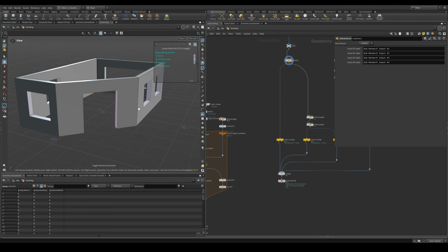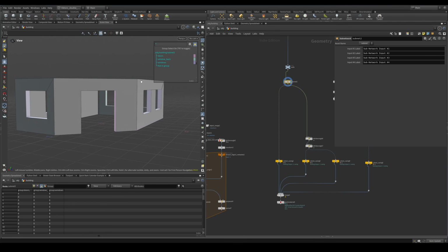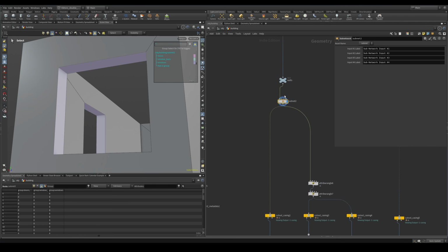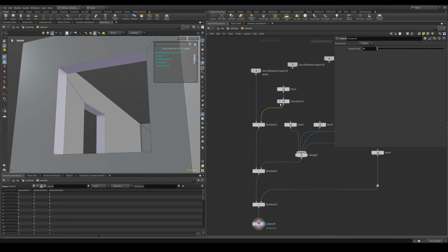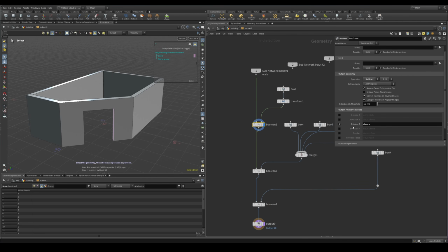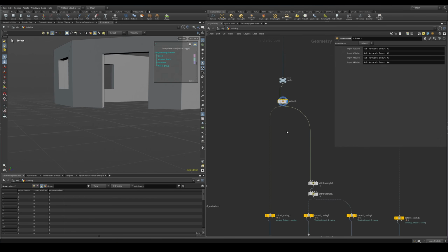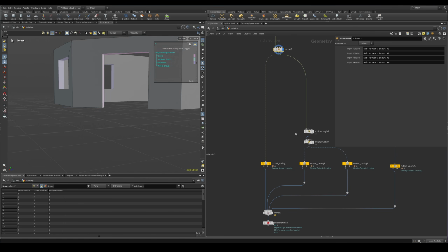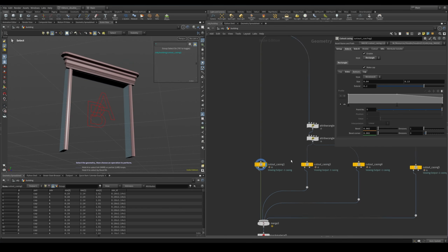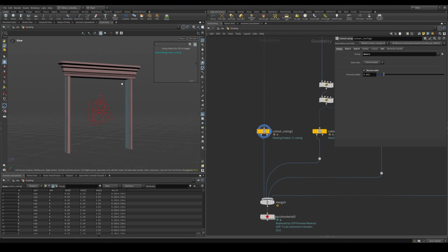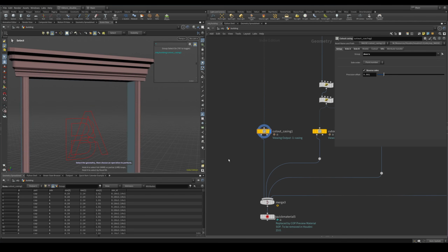Have these basic cutouts, and from the Boolean node, I have made sure that I have saved the cutout groups that usually come from when I do my cutouts with some simple boxes. The Boolean node has an option to save this group, and this group is ideal to be used on the cutout casing nodes. So in this example, I go to the setup and say, actually, I want to use my group, which I have marked as a door. And now we can go ahead and start adjusting these values.